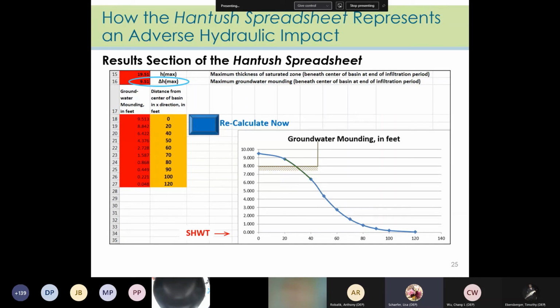So we would double the initial value for T if we halve R. Remember, we don't know the exact rate that R will slow down to, but even if it is slowed by half, we're going to check the mounding for a value of T that is within our maximum allowable time frame. So this is what we mean by stretching the infiltration period.